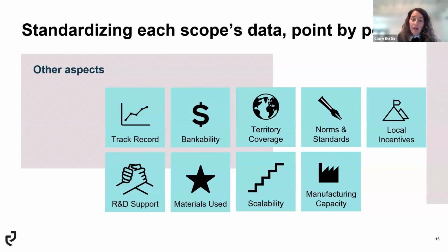And also the way they are calculating the capacity, so the actual volume of hydrogen you will get out of, let's say, a 5 megawatt stack. It's common knowledge that a 5 megawatt stack gives 1,000 cubic meters per hour. But in China, it's going to be less because of the way they are calculating the flow and the energy inputs. So you also want to make sure when you receive a quote that you account for these different norms and standards between the different regions. Otherwise, you could end up with a totally different conclusion if you don't account for it.